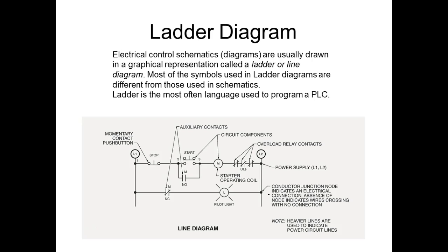No, this is not a motor. This is a relay coil. A motor has a different symbol. This round circle in motor controls is a relay coil. It's got a name. They named it IM. In PLCs, in RSLogix 500, they call them symbols. So what we're going to do is give these devices names.